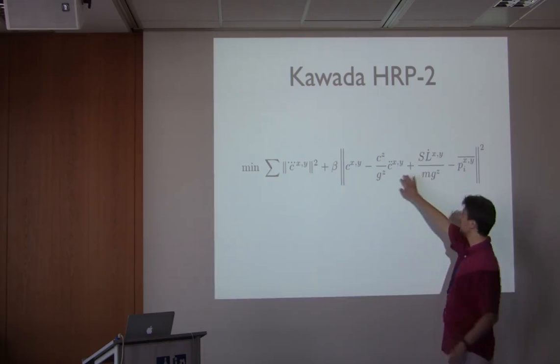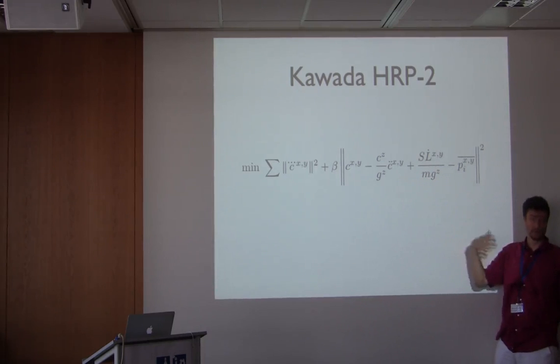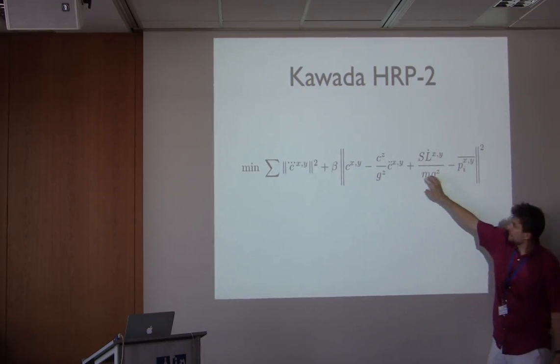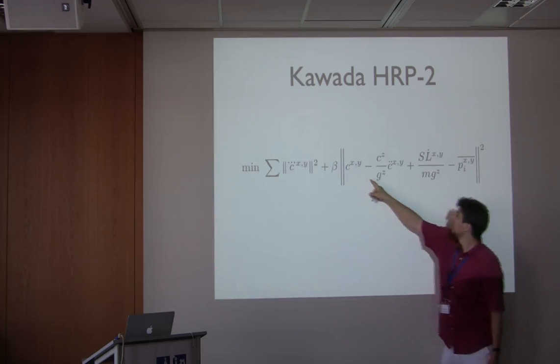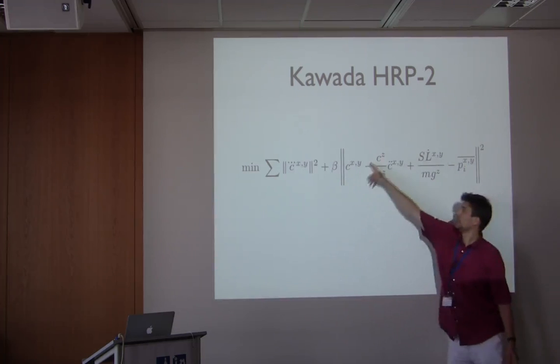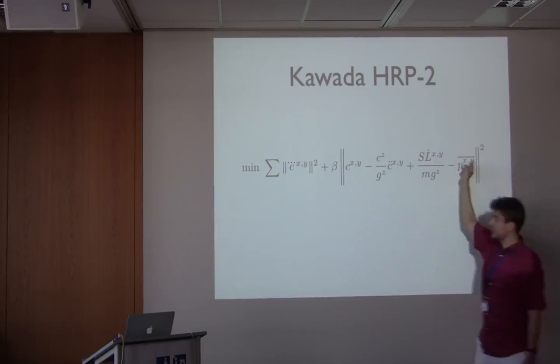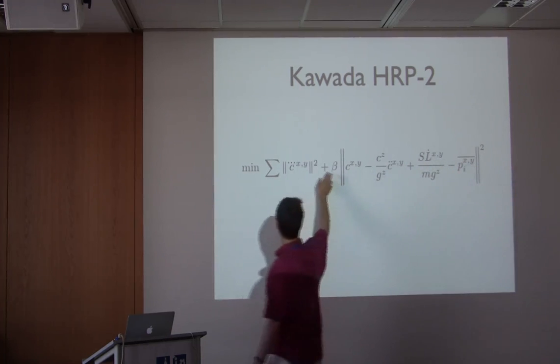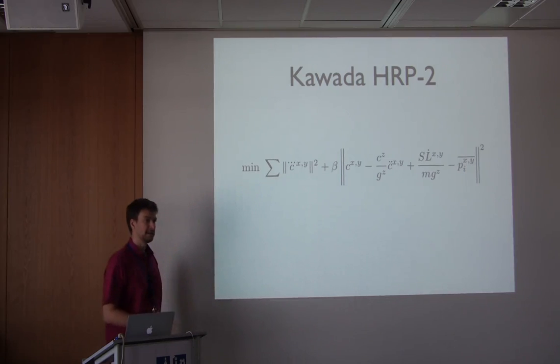Here it has a predefined angular momentum. Then he wants to compute the motion of the center of mass such that the center of pressure is as close as possible to the center of the feet, but at the same time, with some weight, minimizing the third derivative of the center of mass.